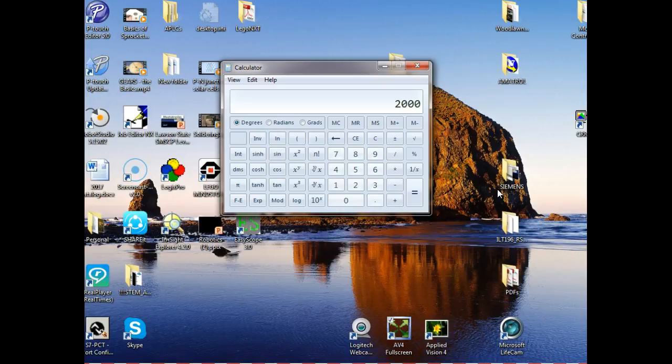So if we were going to bring this into a system, what we have to understand is that most of these encoders are going to be in what? It's not going to be in revolutions per minute. It's going to be in revolutions per second. So the first thing I need to know is how many slots are in the encoder. I know how many slots are in the encoder, right? You understand that? I would have to measure the time. About the only way I know you can measure the time is with an oscilloscope.